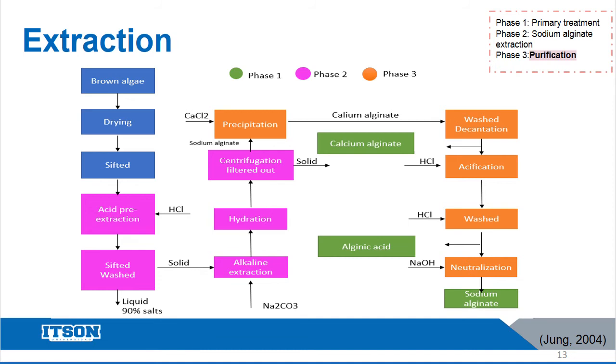Once the compound has been transformed into sodium alginate, it is necessary to dissolve it to facilitate its migration to the aqueous phase. As the product diffuses slowly, it is necessary to promote it by acting in three ways: large amounts of water, increasing the temperature, and stirring the dough.